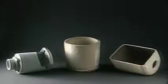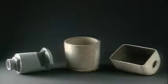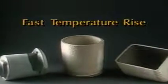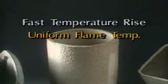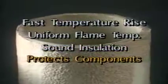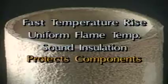Here are three combustion chambers made from soft fiber refractory material. The material makes it easy to achieve a chamber with few or no corners and without cool surfaces. Soft refractory chambers also offer fast temperature rise from a cold start, uniform flame temperatures during steady operation, sound insulation of the combustion noise, protection from intense heat, and rapid heating-cooling cycles.